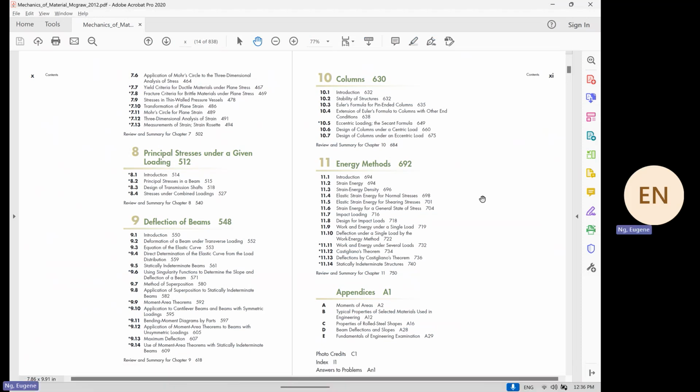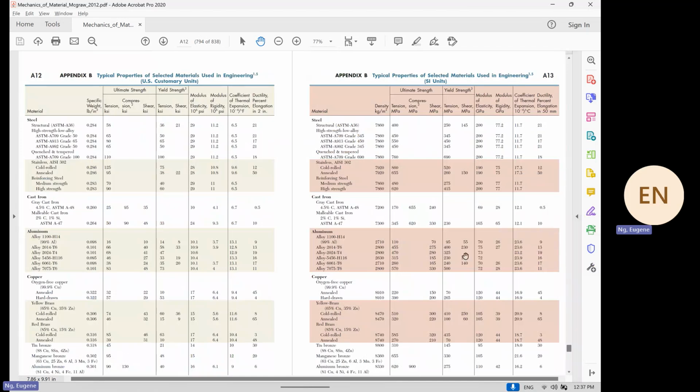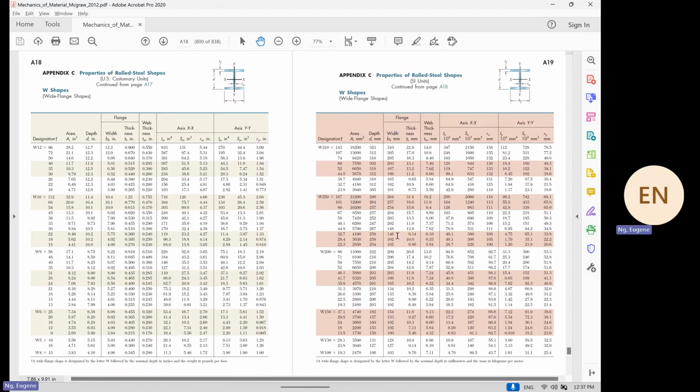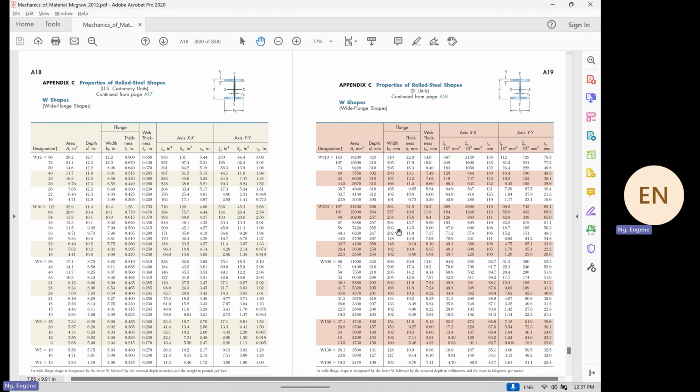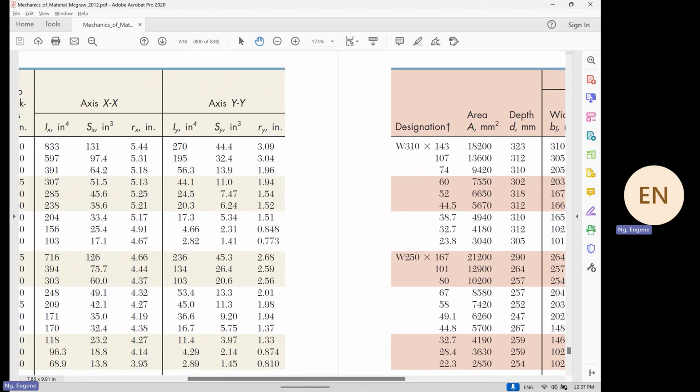If you go right down below on the last few pages, where you have structures, let's look at a typical I-beam. If I were to zoom in, can you see Rx and Ry? Yes or no? That is the radius of gyration, and the radius of gyration is computed by using the second moment of area, I, divided by what? A.